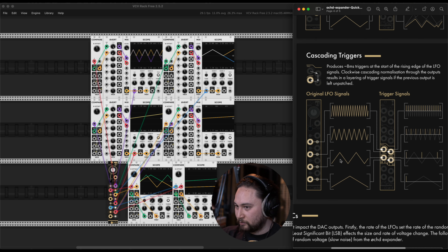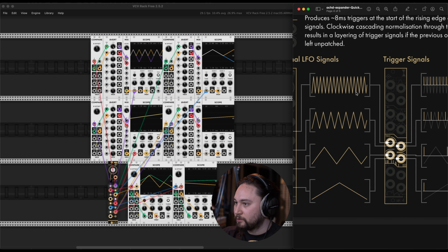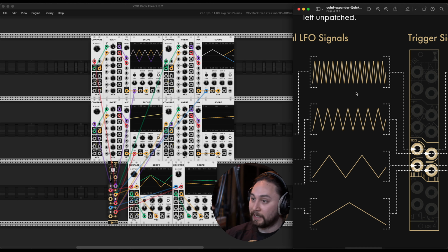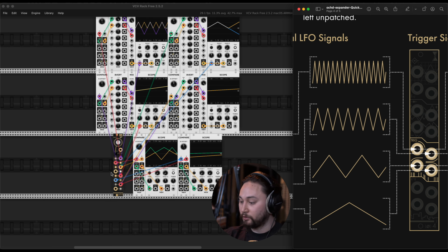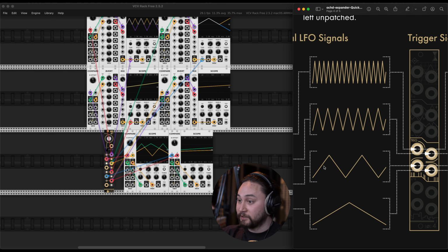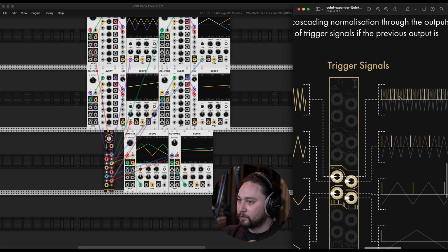So the cascading part will just come down to summing, but what this is doing, there's a way to recreate this pretty accurately. On the actual analog, I'm pulling from the integrator circuit that generates the triangle wave from a square wave flip-flop state. I'm using that raw square, which doesn't exist on the front of the Oct itself, but on the back I was able to extract the raw square waves and work with them as needed. So we're going to be doing a bit of reverse engineering here to gain this square wave effect, and there's something that's quite particular about it.